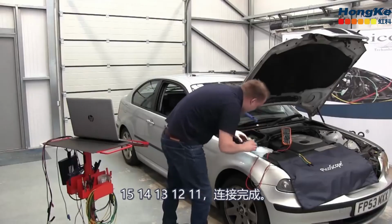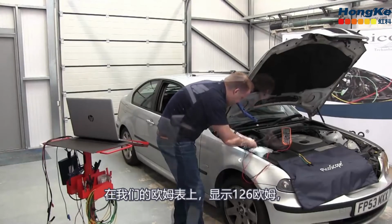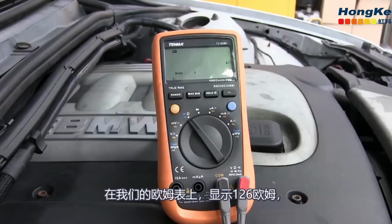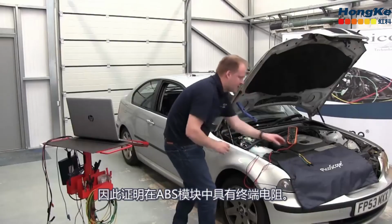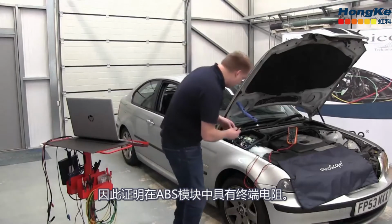Lovely. Okay, so now if we look at the resistance across the end of those two on our ohm meter, right, what are we getting? There we go, so 126 ohms, so lovely, that's exactly what we'd expect. And so that's proving that we've got the termination resistor in the ABS control module.